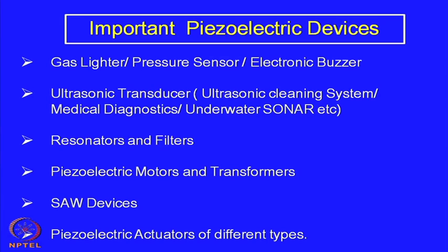buzzers or sensors. By the same principle, one can use a large variety of pressure sensors, load cells of different instruments, and wherever we need to measure the total load or the particular pressure, one can use this kind of a system. We are not going into the details of the designs, but just using the basic principle of the piezoelectric coefficient, one can design different kinds of load cells from a few grams to several tons.